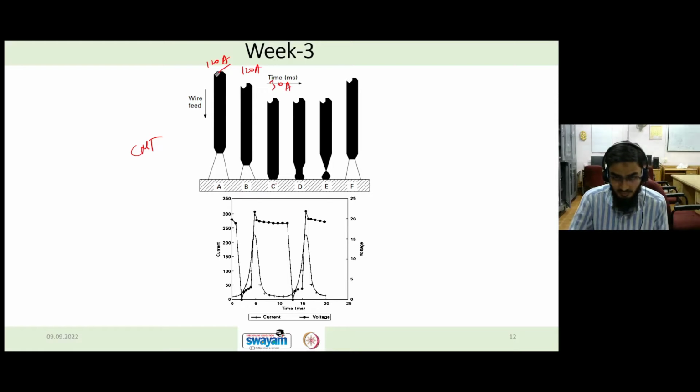Let's say we can call it 30 ampere. So the molten droplet will form and now we will retract. We are bringing it closer and now we are taking it out. During removal of this filler electrode, we will slightly increase the current. You can see the current graph: we make it very low, but again slowly increase the current while retracting. So here is the process of bringing the electrode closer to the workpiece, and this is the process while removing the filler from the workpiece.